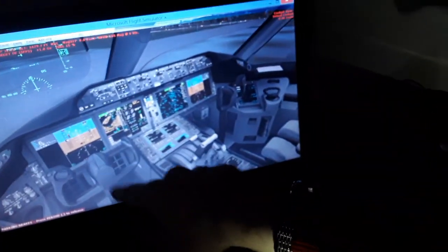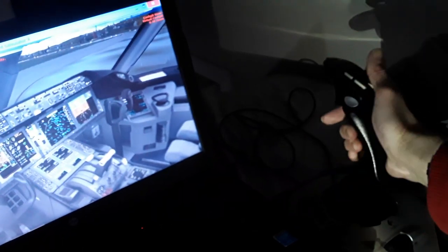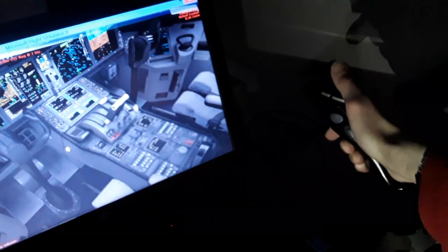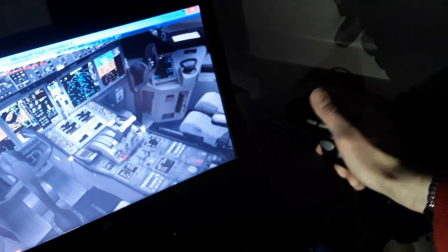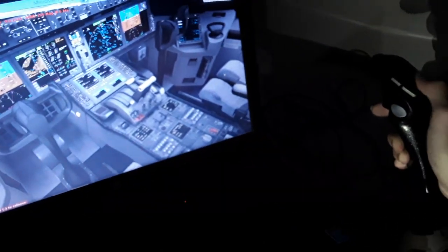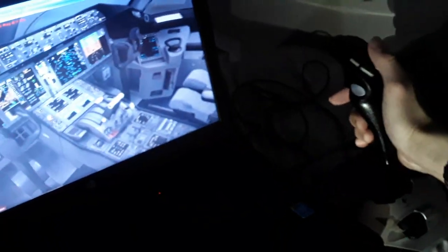So we see the control wheel for the longitudinal or roll axis of the aircraft, left and right turns over here. So we have full flight controls: the elevator, ailerons and spoilers, left and right turns, rudder and the nose wheel steering. On the ground, the nose wheel using the rudder pedals. We have also the horizontal stabilizer trim over here. As you can see, all flight control surfaces move together, both the captain and the first officer in the Boeing aircraft. They're interconnected. Also the rudder pedals are interconnected.